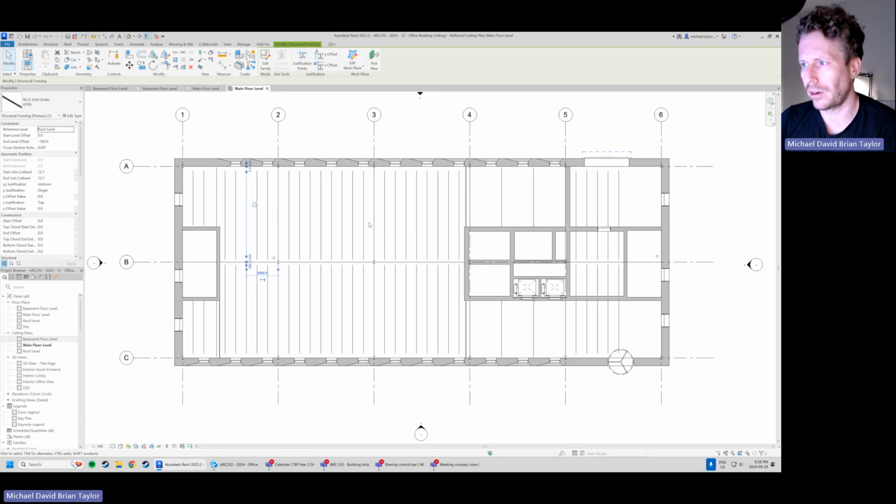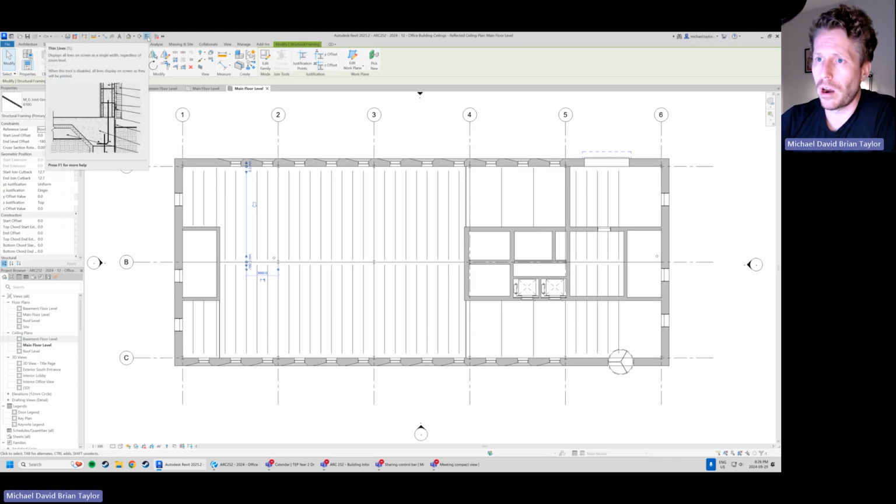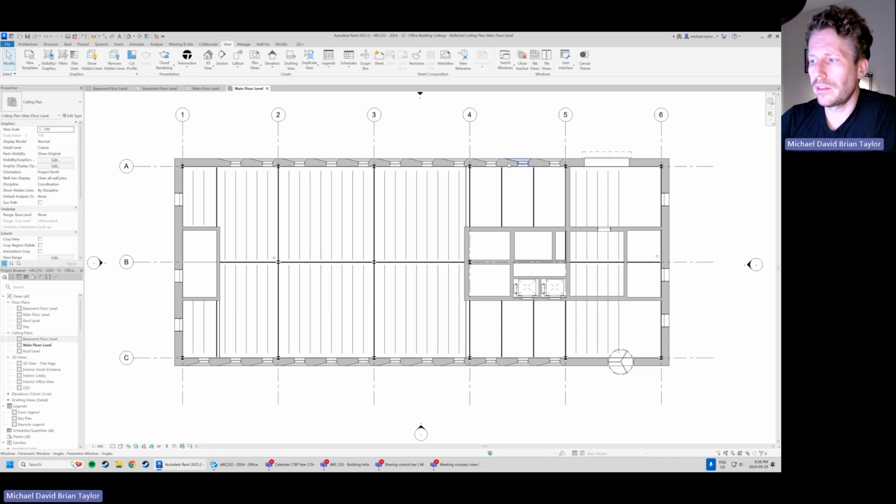So I want to encourage us to just have an idea of how to demonstrate using those structural pieces. How do we get the structural members, these little structural beams, to turn on or turn off inside of our model? The first thing I'm going to do is turn thin lines back off, so we'll have our regular lines showing up. Remember, thin lines up here in our quick access toolbar, hit that little thin lines. And what we can see now is everything comes back in.